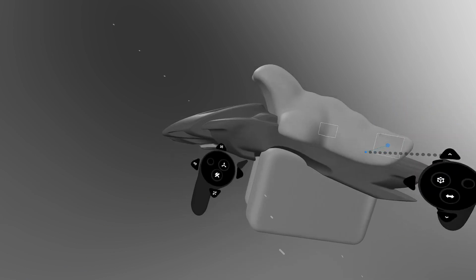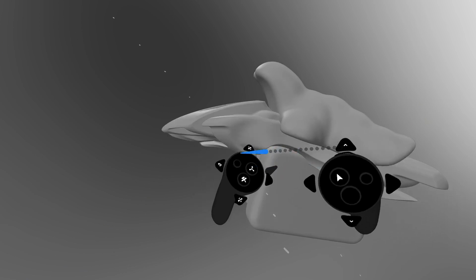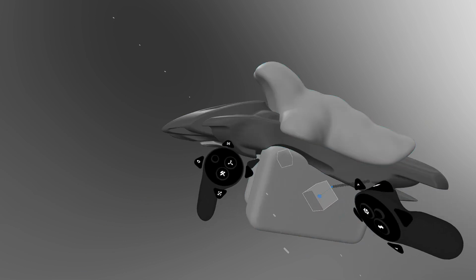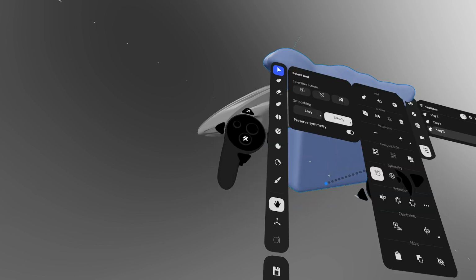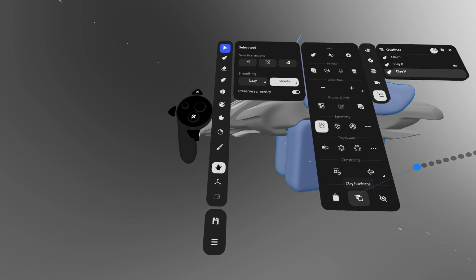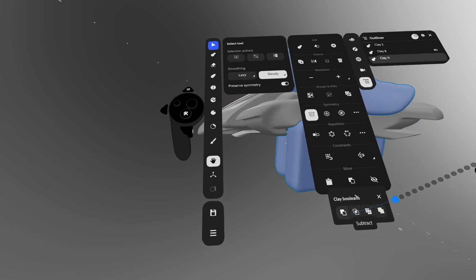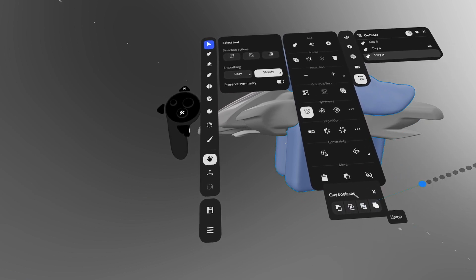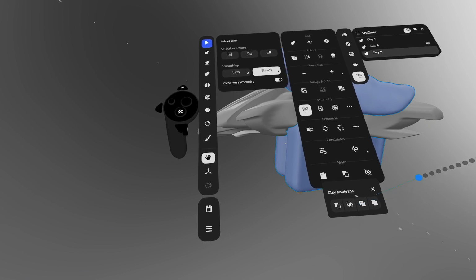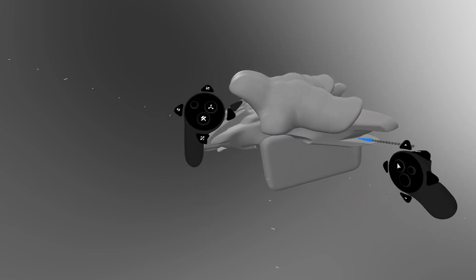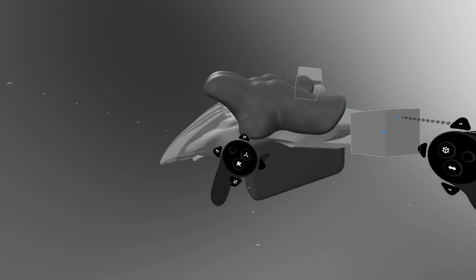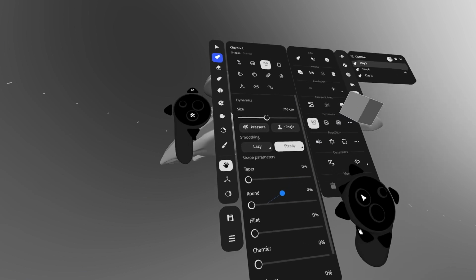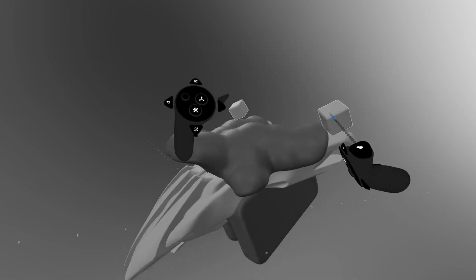But now that we've done that, we can scope out. Down and up on the left thumbstick will let you scope in and out, right? But we got this here. So we select this object, go to our menu. There's a Boolean menu, clay Booleans. And we can do subtracts, intersects, and splits. And we can do unions as well, which is kind of pointless. I want to point out why this is pointless, though. Because, let's say I was doing a quick cube on this shape here. And I want to just round it out, fillet it, and maybe I do a little...